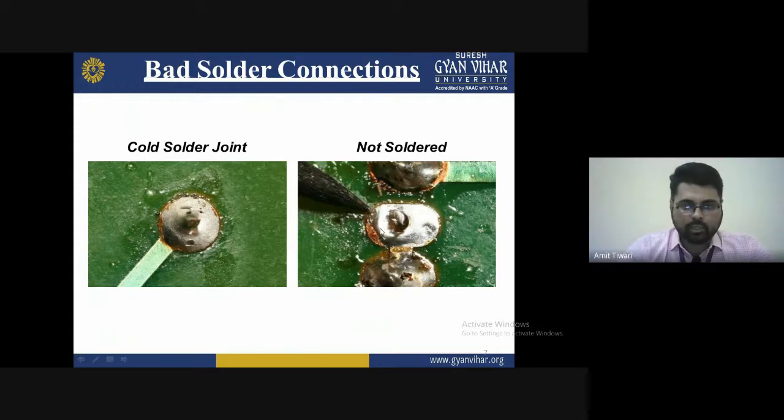So it is a wastage of solder material, filler material, time and power consumption. So during machining, keep in mind that when you are doing soldering, you must make a perfect joint. And the perfect joint is obtained by completely filling the filler material into the required gap.